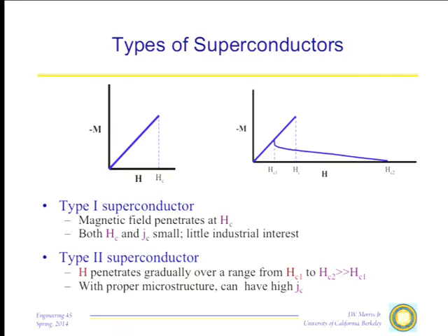The highest dislocation densities you can get into a material usually are by machining it and just taking the shavings. You know, if you use a cutting tool and you start machining the material, little shavings come off. They're very heavily deformed and have very high dislocation densities. So he says, what I'm going to do is just machine a bunch of niobium and create a whole pile of shavings, pack the shavings into a hollow tube, draw the tube down into a wire, and then have real good properties. So I got the tedious assignment of picking up all these little shavings and packing them in the tube and putting plugs on the end and drawing them down.